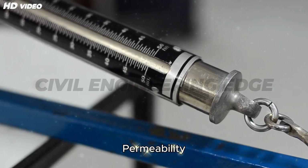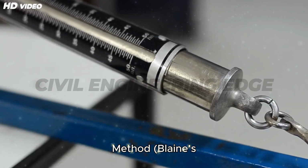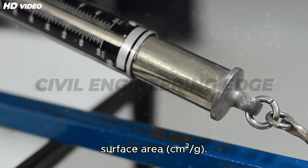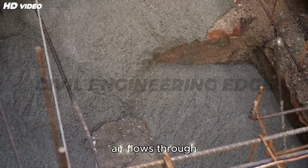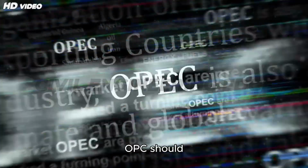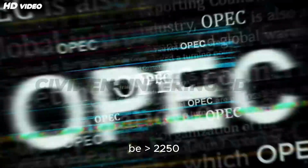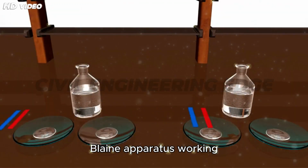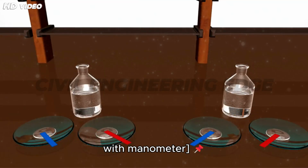B. Air permeability method, Blaine's apparatus. Measures specific surface area in square centimeters per gram. Based on time air flows through compacted cement bed, OPC should be greater than 2,250 square centimeters per gram. Visual: sieve shaker, Blaine apparatus working with manometer.